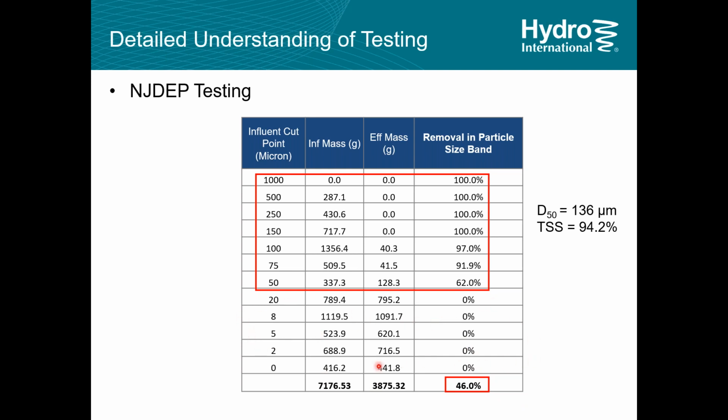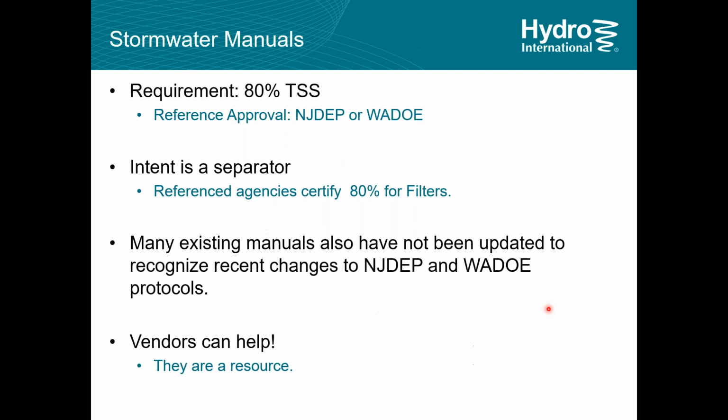Well, you're never going to get that. And really, the application of this equipment, if you're using a separator that's designed to get down to about 50 micron, shouldn't be used on a site where you're looking at 20 micron or less. So it's a horses for courses type thing.